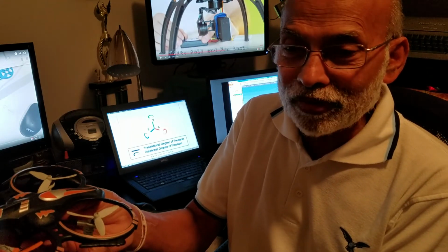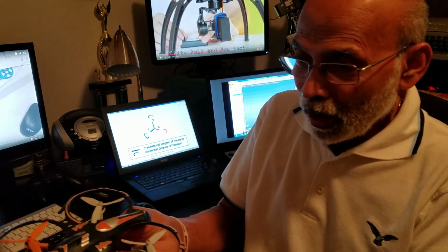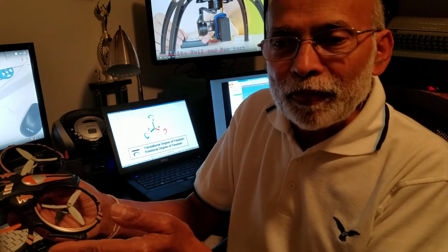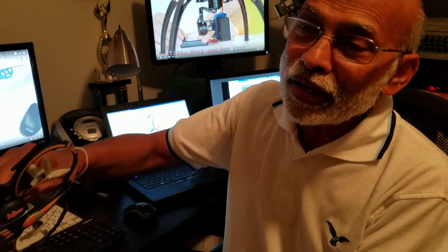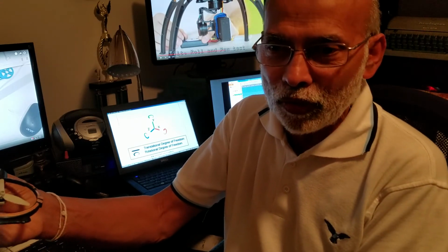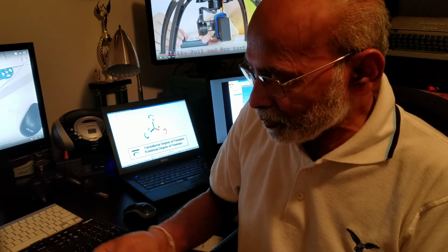And then how about D? Let's think of D as damping. Let's say you take an aggressive turn, and you want to be aggressive, you're going to be quick, but at the same time you do the D value, meaning inject a little drag, so that as you do the aggressive turn, it also gets back as soon as possible to the level that it can do the flying in a smooth fashion. So that's pretty much about the PID in layman terms.